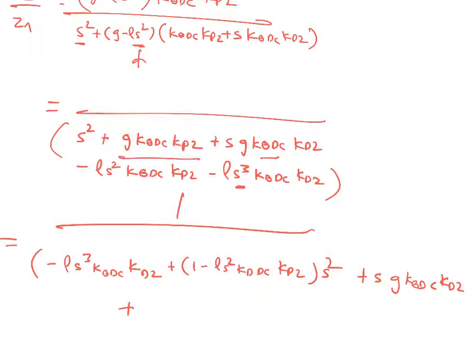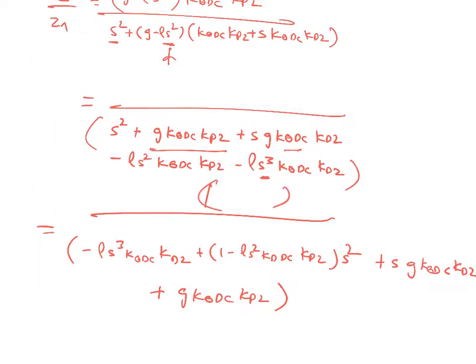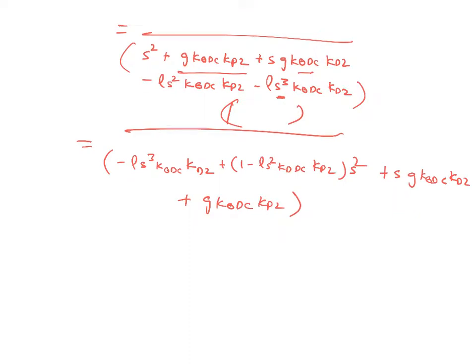This one. So that's G K theta dc K pz. That's our denominator; whatever we have, there's some numerator and we have a denominator here. Good? So now the question is, what should the closed loop look like? How many poles will this have now? Three, right, because it's a third order equation.